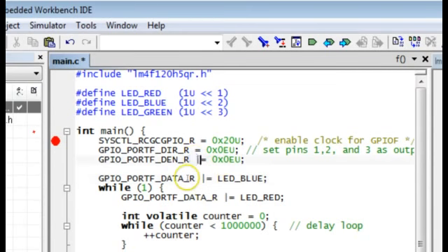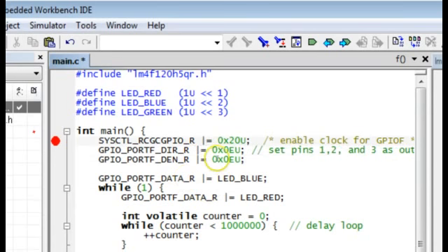Actually, all of the lines above also perform setting of bits in various registers, so they too should be coded with the bit set idiom. Please remember, however, that you need to check in the datasheet that the registers have read-write permissions. And finally, you can use the LED macros to further improve the readability of your code.